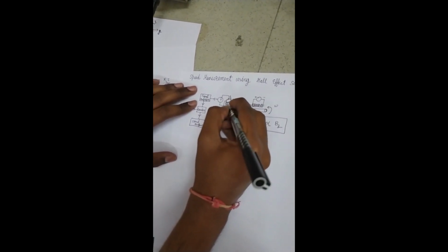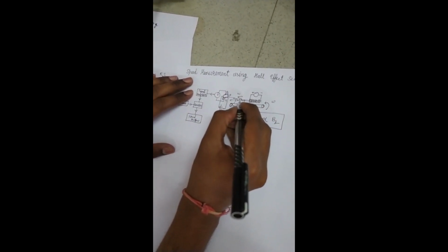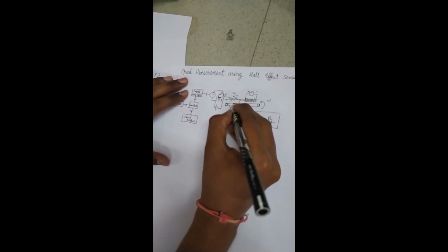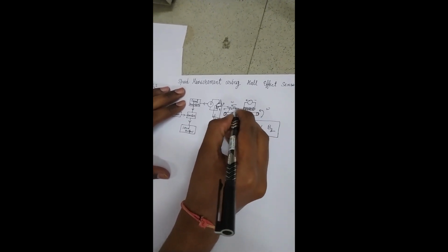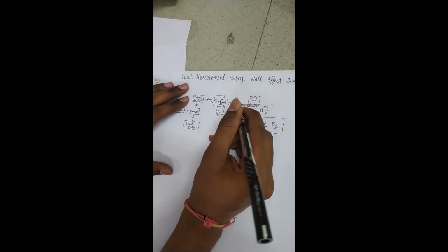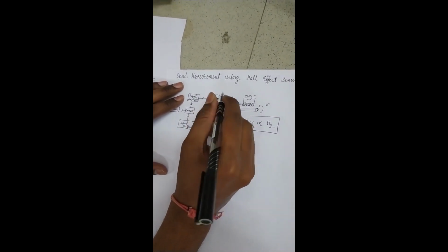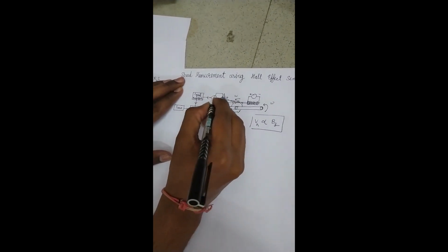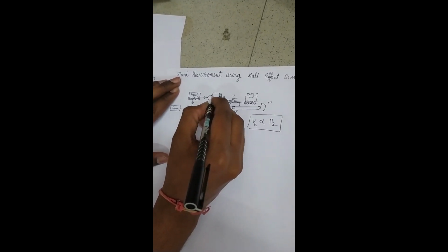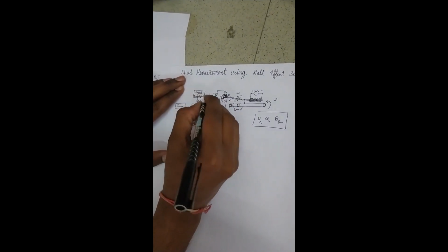By measuring the Hall voltage across A and B, not just the Hall voltage but its variation due to the rotation of the tooth wheel, since as the tooth wheel rotates, the teeth come in front of this solenoid, and this causes the magnetic fields to concentrate within the wheel a little, and as a result, at the receiving end, where the Hall effect probe is there, the magnetic field changes, and this change can be measured by the voltmeter, and by sensing the change in the Hall voltage with time and amplifying the signal, we can count the number of peaks.